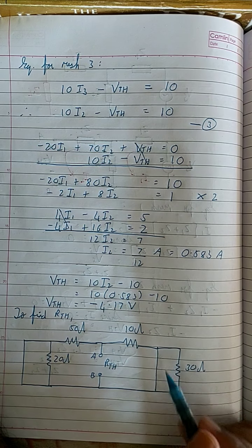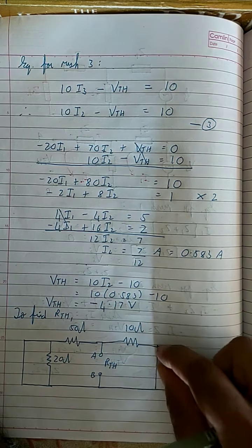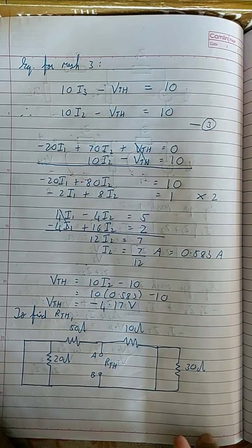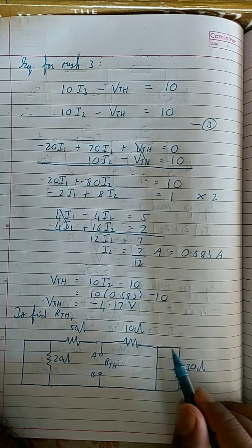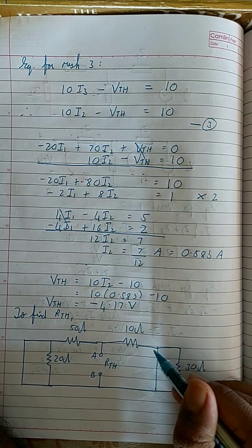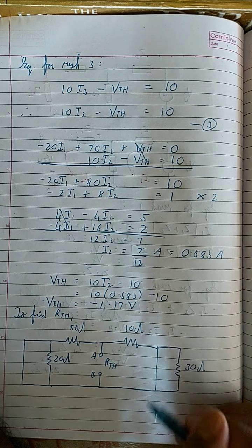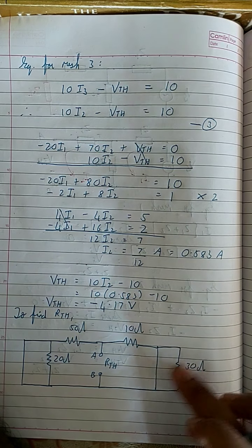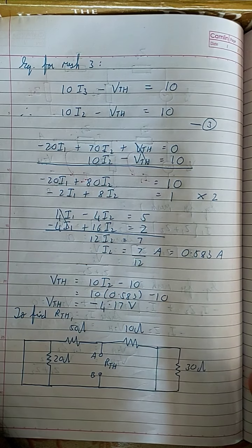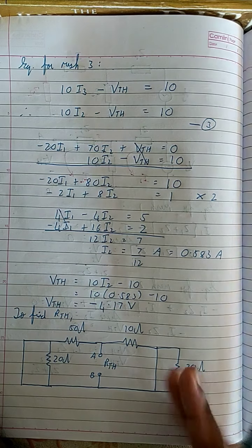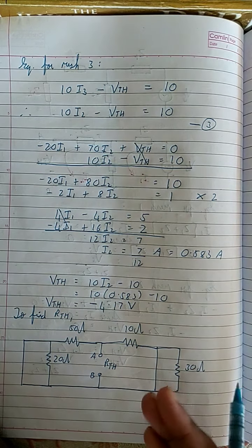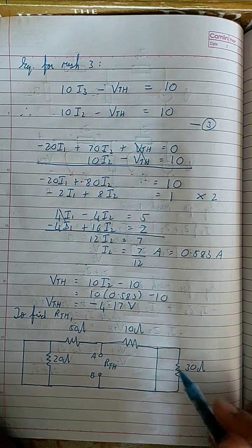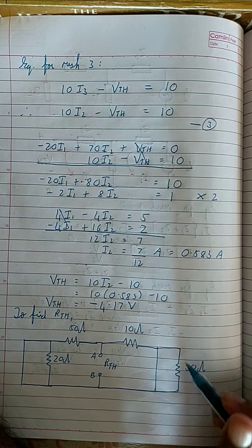It's a short connection, right? This end of the resistor and this end of the resistor are shorted together because they are all in one connection. So this entire thing is just one connection, which means no current will flow through this resistor, because this is the easiest path for the current to flow, right? This is the easiest path, which means this resistor can be discarded. Since no current is flowing through the resistor, there is no need of finding the equivalent resistance by using that resistor, right? Because the overall resistance is equal to 0.